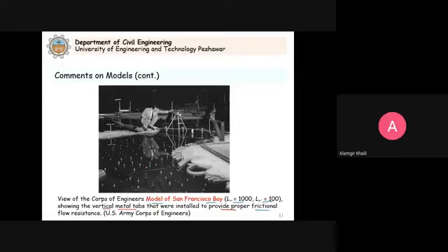This is now the issue we have to address. So there is no simple rule for this. Is any distorted model lacking proper similitude? As you can see here, the scales are not the same. Now there is no simple rule for this. We must adjust the roughness by trial until we judge the flow conditions are typical of those in the prototype.